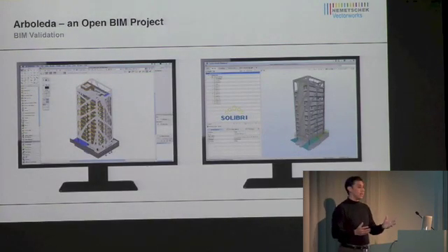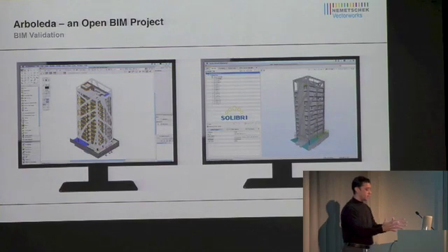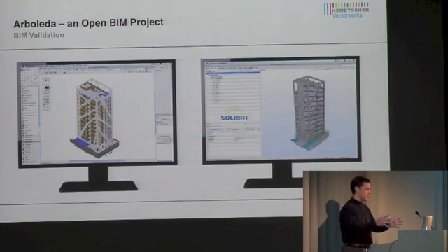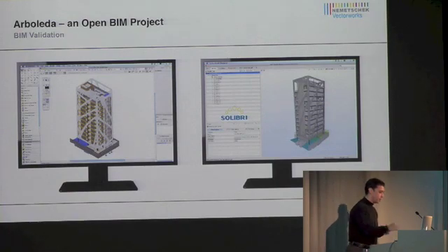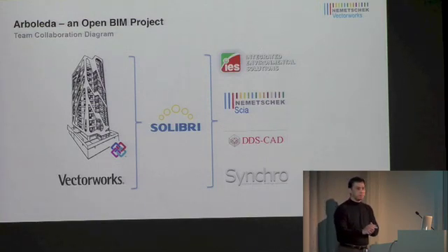And what I wanted to share here is, it's really something. It's just a new feeling. It's really nice to have a BIM package and a BIM tester side by side. So you may have the opportunity to do this, but it's just a new way of attacking a project. Now, we have our IFC creation done by Vectorworks. I use Solibri Model Checker for testing the model, and it's ready to be shared with others.